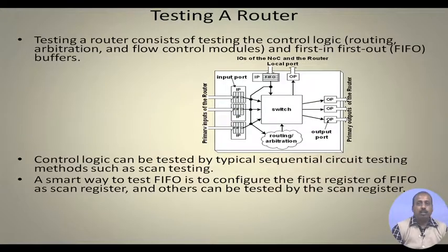But that will increase the complexity of individual routers, and as we have said, the individual routers are going to be very simple. So, this buffer depth cannot be large. Normally it is kept as 4 to 6, not more than that, and as a result a packet gets distributed over flits, and some of the flits of a packet will be available at a buffer of a router.